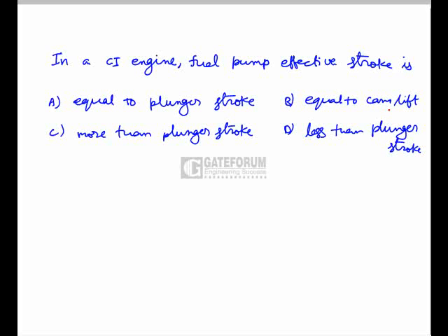In a CI engine, fuel pump effective stroke is. So here the options are equal to plunger stroke, equal to cam lift, more than plunger stroke, and less than plunger stroke. Here the right option is less than the plunger stroke.